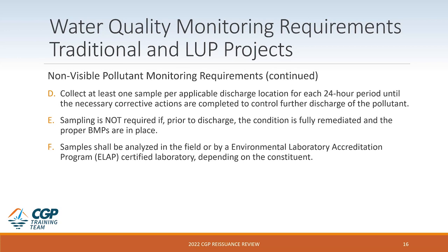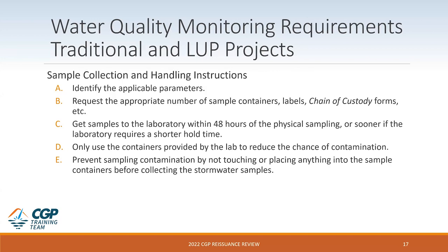Sampling is not required if, prior to the discharge, the condition is fully remediated and the proper BMPs are in place. This would need to be documented. Samples shall be analyzed by an ELAP lab.